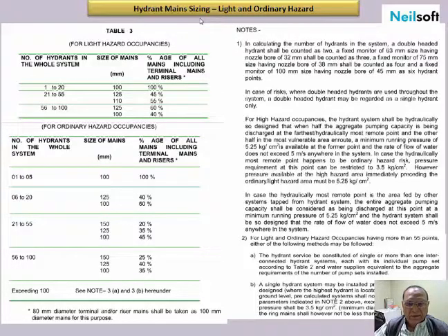Further to that, if you happen to have an external hydrant, in that case the internal hydrant mains will remain the same as what has been explained in table 24, but for sizing the external hydrant we have to abide by these tables, which explain that for 1 to 20 hydrants, as we had discussed earlier, for the pump's flow and the head, 100 mm will be the riser and the mains diameter, and when you have 25 to 55, it will be 125 and 110.